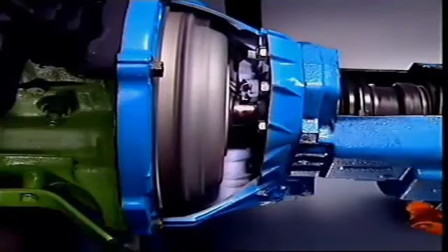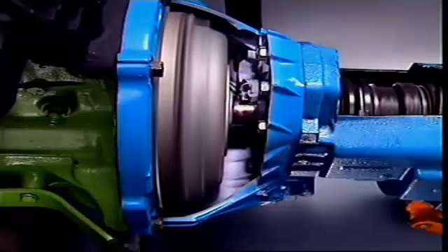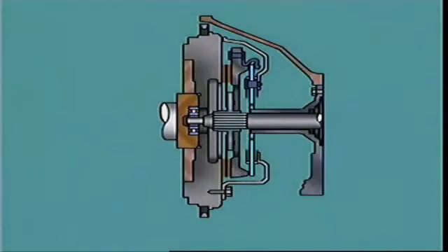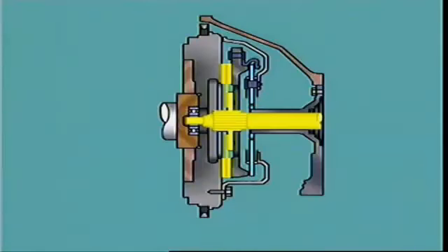With engine rotation, the flywheel and clutch assembly rotate as one unit. Engine torque is transferred from the flywheel through the friction facings to the splined hub and into the transmission. Moving a clutch pedal operates the release mechanism to control the flow of torque between the two units.